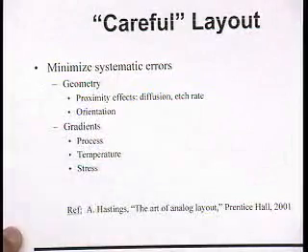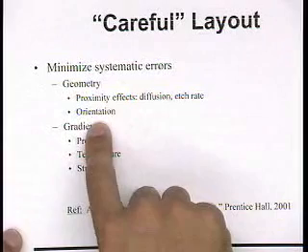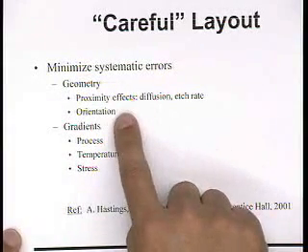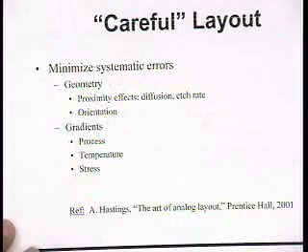There's two kinds of techniques. We want to minimize proximity effects, orientation effects, right? And that means that we want our transistors to be surrounded by the same kinds of devices so that they match really well. So I can very easily introduce a mismatch if I put one device close to a big well and the other device not close to a well, right? Because the etching will be a little bit different close to the well, and there'll be a stress from the well, and all sorts of things will change one transistor relative to the other. So I don't want to do that. Those are the things I can do to help here.